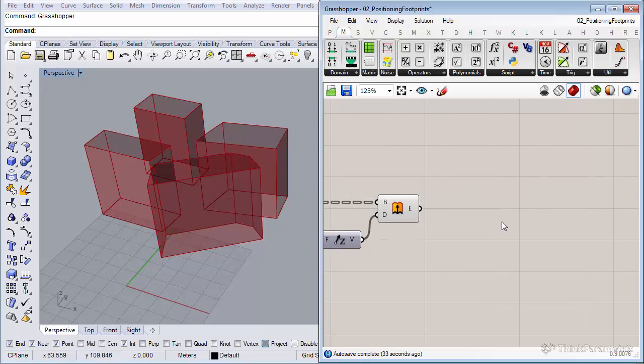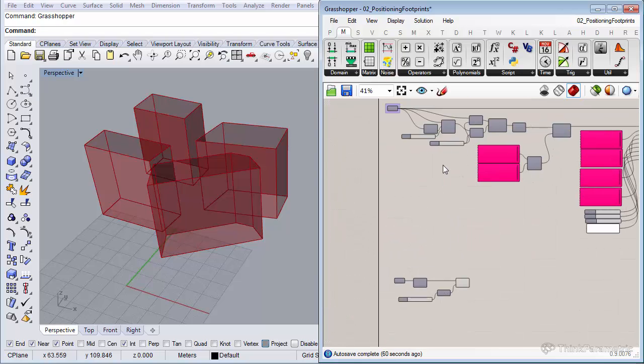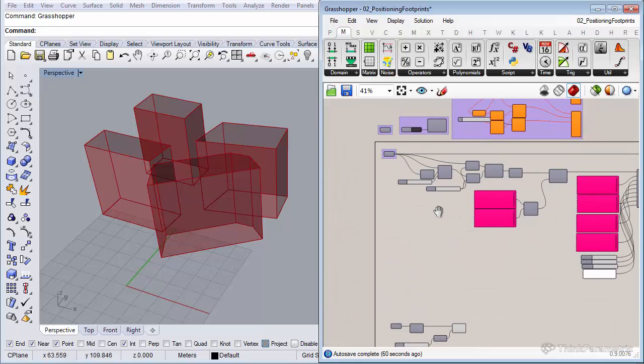And before we start using the divide surface component to populate the surface with points, we need to shrink those surfaces a little bit. That is for the reason that if we're going to emit the rays, the points that are all the way on the edge, sometimes they don't intersect with the surroundings. Let me turn on the context to show you that.